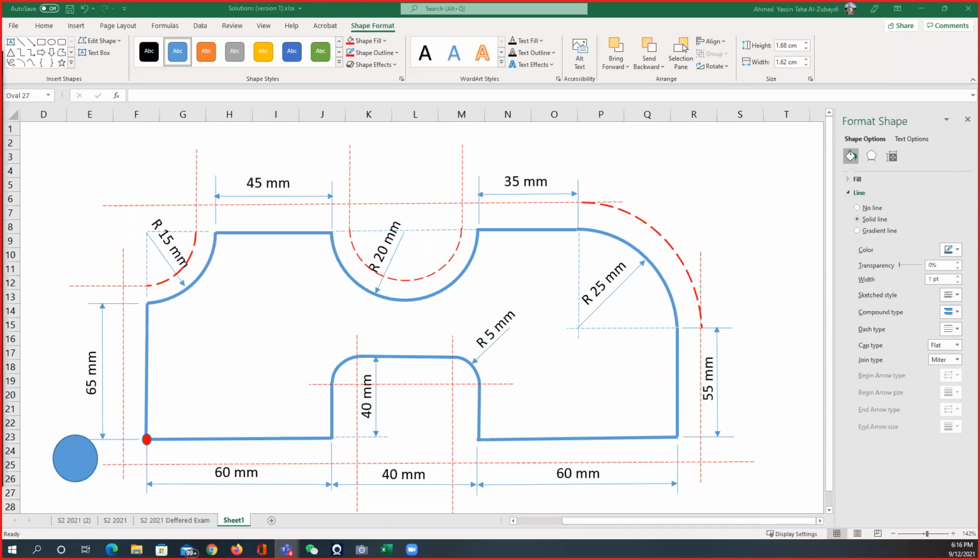Go ahead, be brave. Type what will be the coordinates here. Exactly. So we are going to have point number 1 at minus 5 x, minus 5 y. I'm not going to worry about the Z now. I'm going to talk about the Z later. Or I can tell you that the depth, the thickness of the workpiece, is going to be about, let's say, 5 millimeters. Okay, so the point here is going to be -5, -5, and -5.